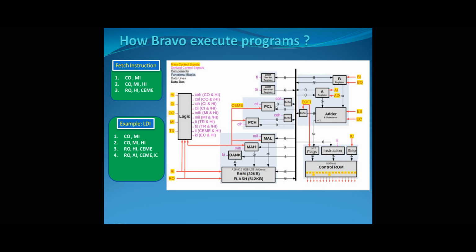If you remember, we said that we needed 2 cycles, for example, for the program counter to put the content on the bus. So if we really wanted to manage that through 2 different signals, one signal for the high byte and the other signal for the low byte, then we needed to have 2 signals coming out of our control logic. However, what we have done here is that we get a HI signal, and then by combining the HI with the counter out, we could come up with those 2 signals.